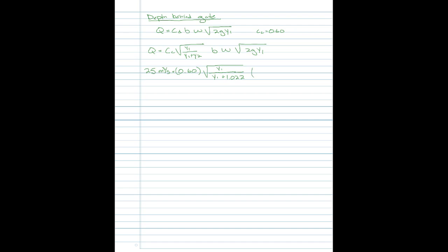And the width of the channel is 5 meters. The gate opening is 1.703 meters. And the square root of 2 times 9.81 times y1.